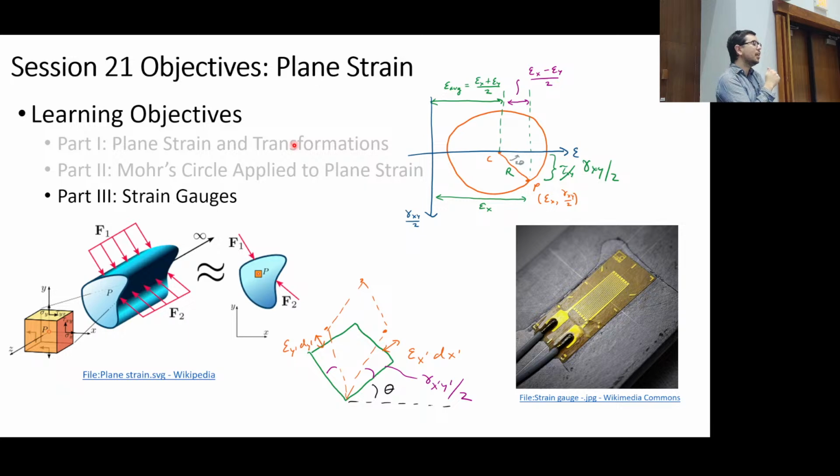Correct. And so if you apply a force in a way that it creates a bending moment, and the structure is experiencing a bending moment, there's going to be some type of bending stress associated with it. And we know from the flexure formula that sigma is equal to negative My over I. And y is the distance from the neutral axis. So bending stresses are going to be highest at the surfaces, typically. Okay, so that's one reason. What's another reason?